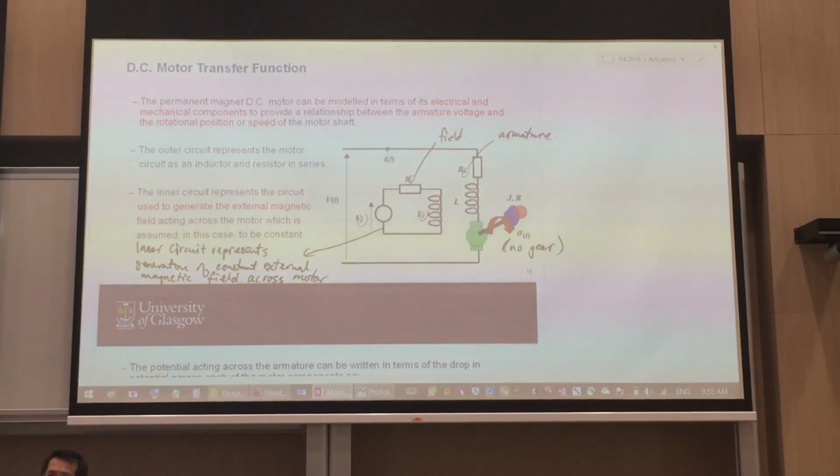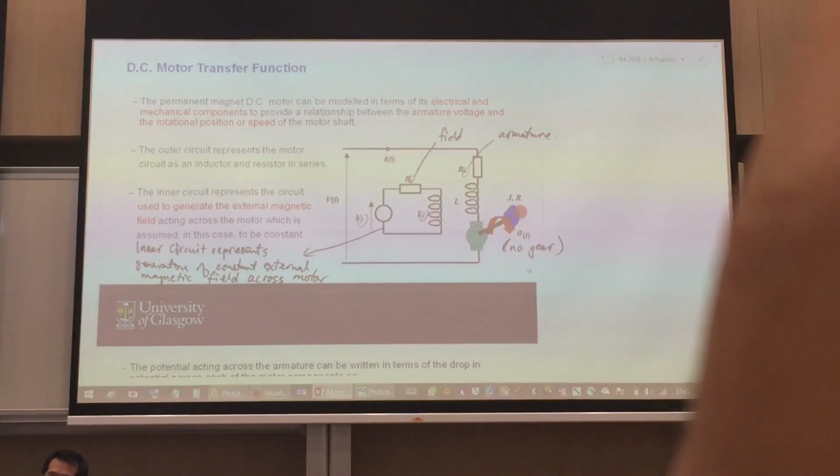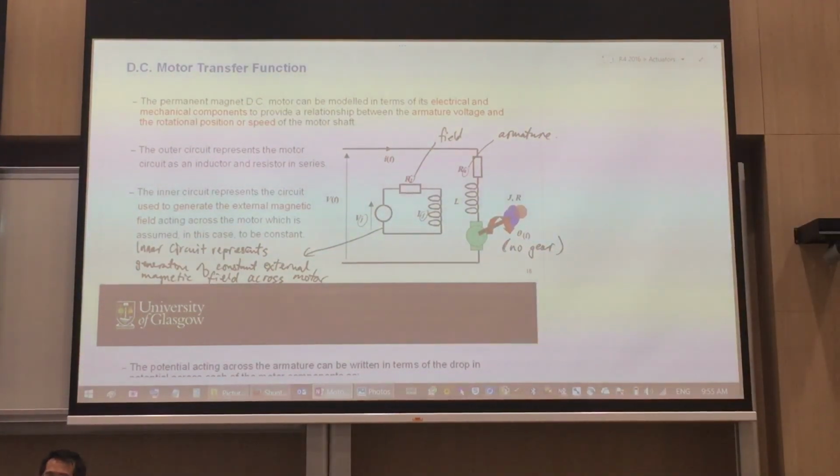Had we not used PWM, we would have to use the gear reduction ratio on the motor. And if you have gear systems in there, like older washing machines, there's a higher chance of it breaking down, because more mechanical components means more chances of failure. So that's why a direct drive motor lasts longer.